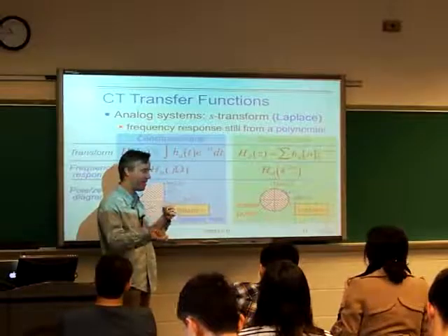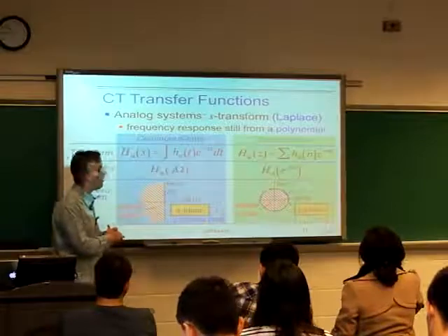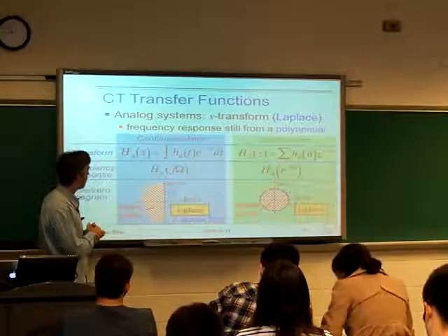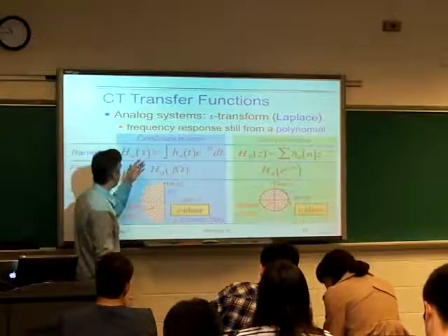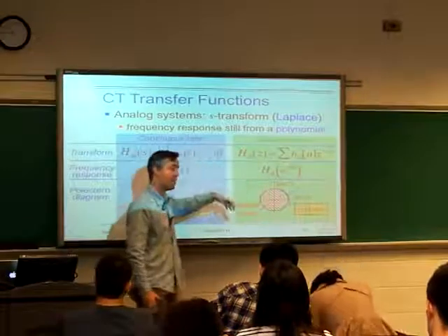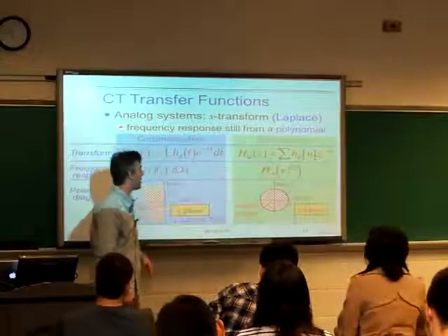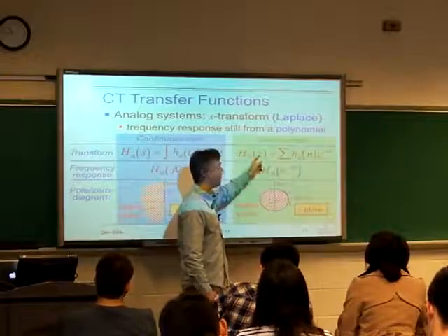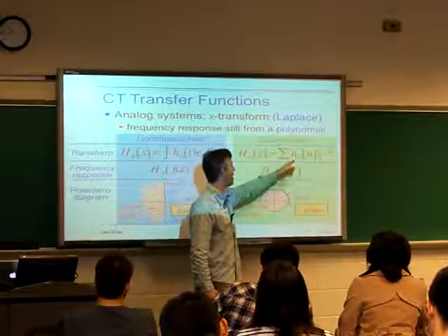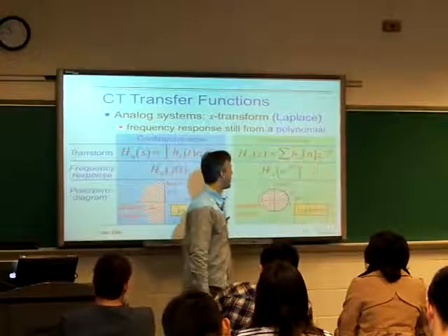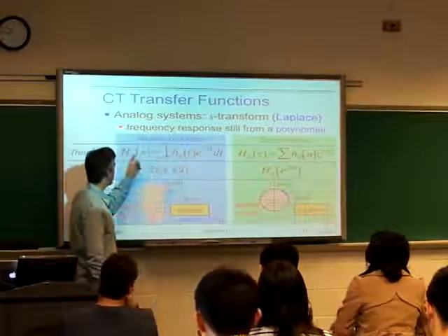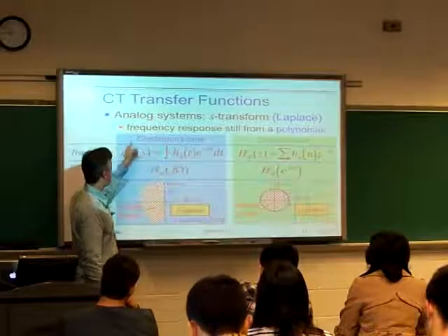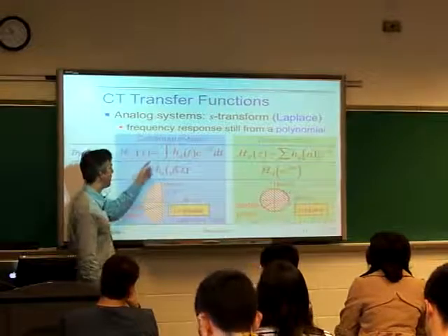quickly refresh our minds and switch gears into this continuous time, this Laplace domain of thinking. So here we've got the continuous time and the discrete time. This is just to remind ourselves what this relates to. In discrete time, we had our systems defined by the Z transform, which is defined here in terms of the impulse response of the system. This is the equivalent in analog. In the analog continuous time domain, we have the Laplace transform, so it's a function of S, this transform domain variable.